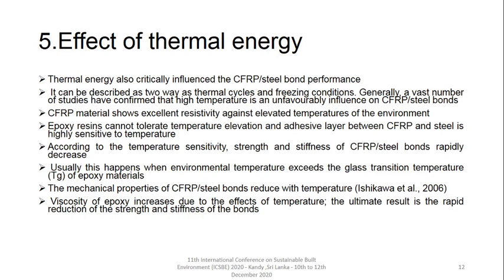The mechanical properties of CFRP-steel bonds reduce with temperature. Viscosity of epoxy increases due to the effects of temperature. The ultimate result is the rapid reduction of the strength and stiffness of the bonds.